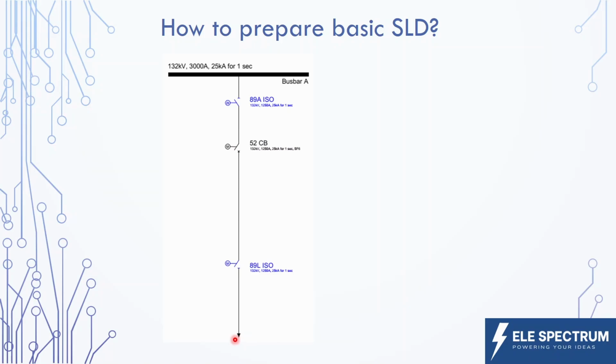Generally, in a substation, you have digital signals for disconnector and also for circuit breaker to check if the circuit breaker or disconnector is in open or closed position. But when you want to do the maintenance of the system and enter into the switch yard, it is necessary to have the visual disconnection of the circuit, and that's why these disconnectors are important.